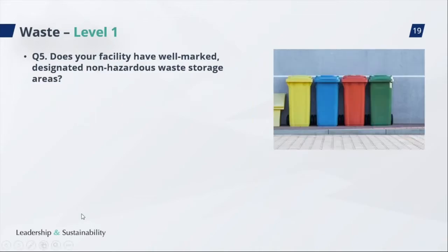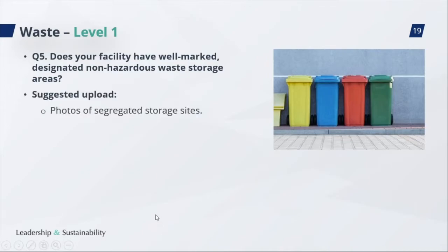Let's go on to the next question here, which is question number 5, which asks you, does your facility have well-marked designated non-hazardous waste storage areas? Non-hazardous wastes can pose contamination risks, for example, pollution, waste being dispersed by the wind, food waste, leachate, etc. And finally, this causes risks to workers by means of fire or sharp objects. Waste shouldn't be kept for too long and in too much quantity. Any site where waste is concentrated and stored even for a short period of time may be a potential source of ground and groundwater contamination.